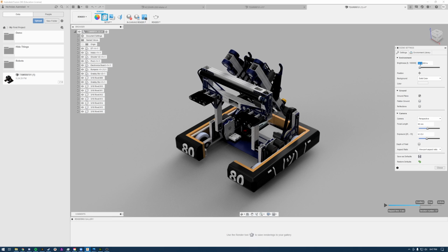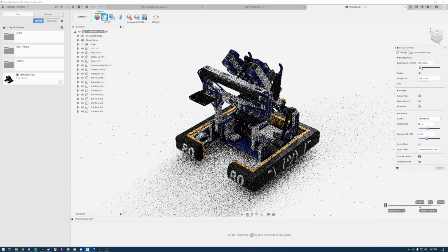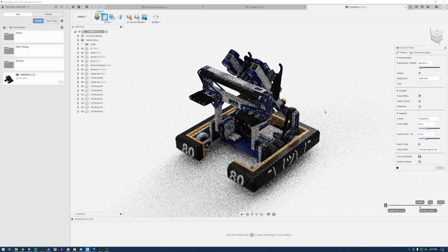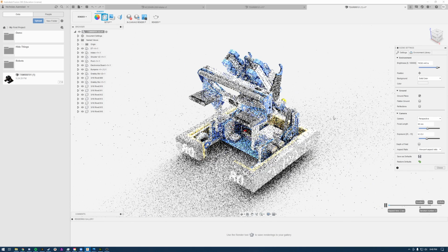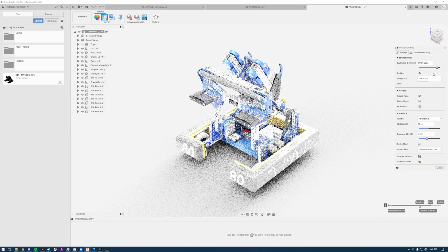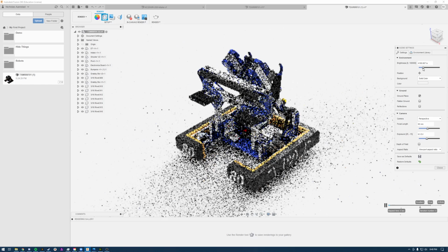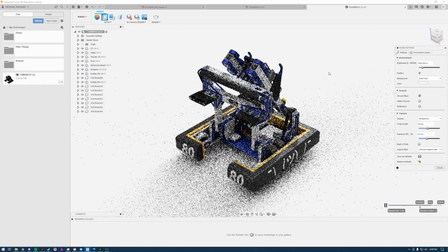And we'll also pump up the lux, which is just the brightness. You can see as I do that, it's re-rendering things. And that's part of why I like to have the viewport on, because it's a little bit better at telling how the light is going to hit it, which can be kind of hard to do otherwise. So you can see I can really crank this up and make it look way too washed out bright. We're gonna pop this down to, I don't know, 3500 lux.